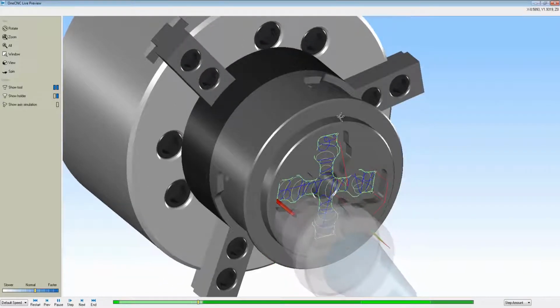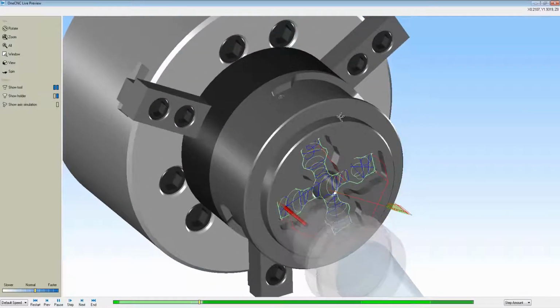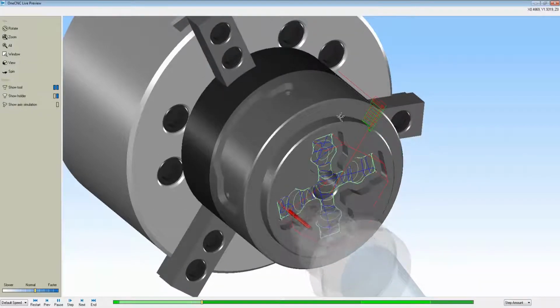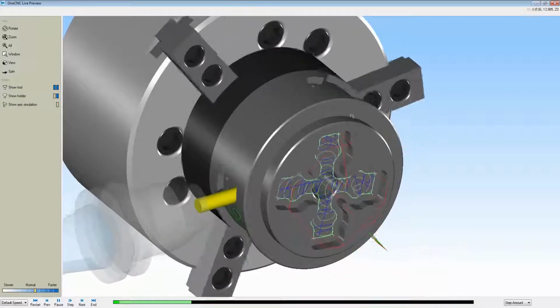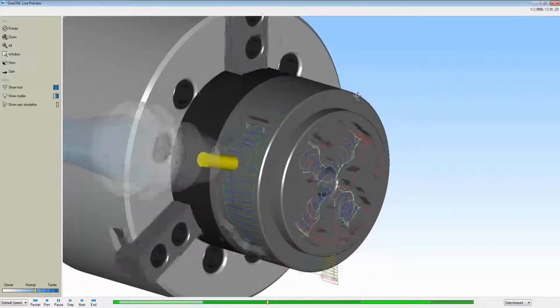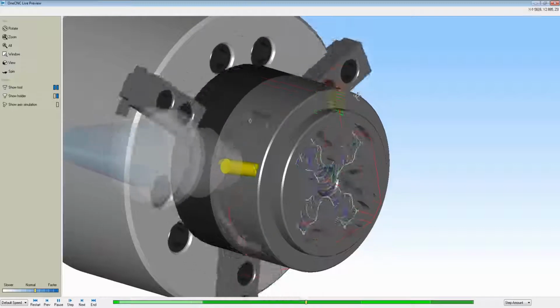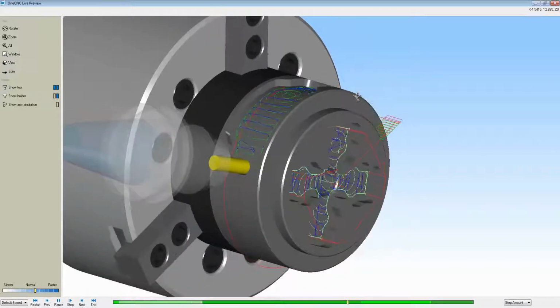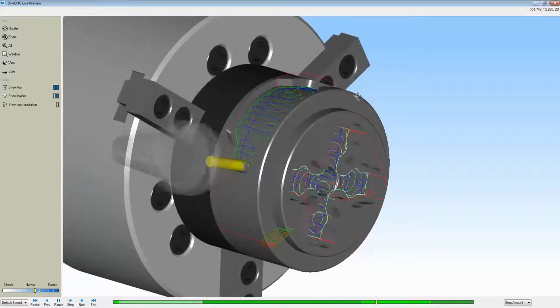And of course OneCNC can output CAD cycles or long-handed G-code for this. It's very nice. Now we'll drill that center hole and then use a chamfer tool to chamfer the hole. Now we've switched tools to a radial end mill, and we're performing some high-speed machining as well on those pockets. We'll switch tools and then we'll perform a finish cut on both pockets.